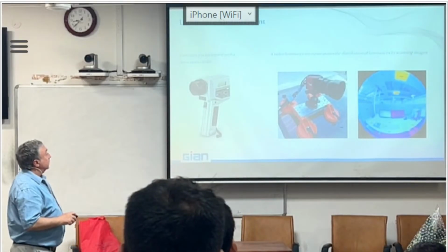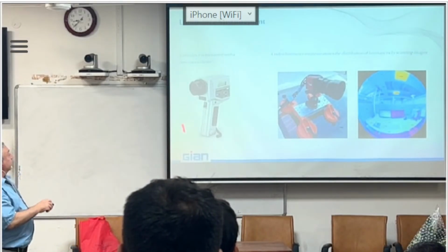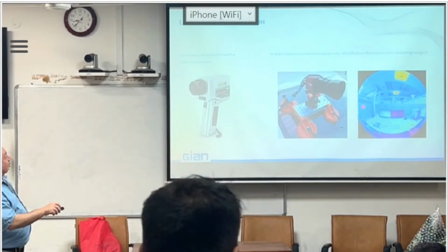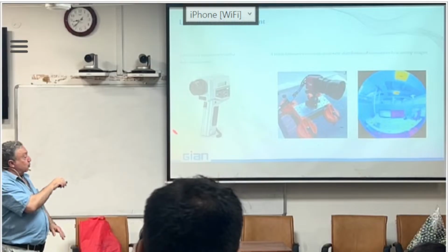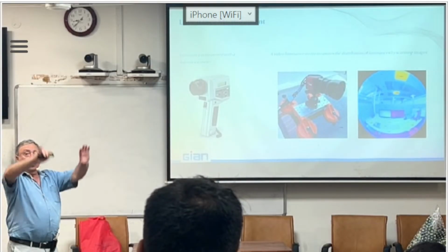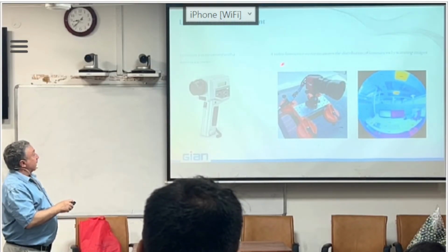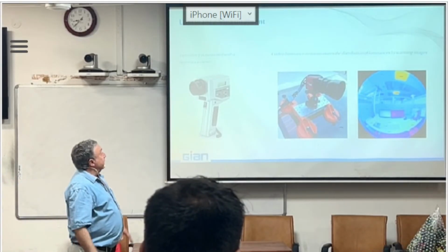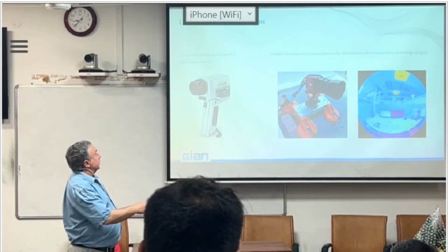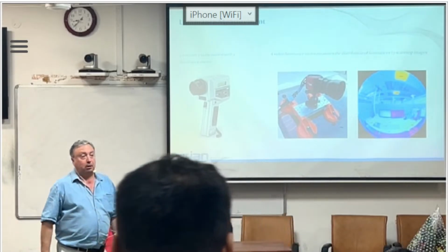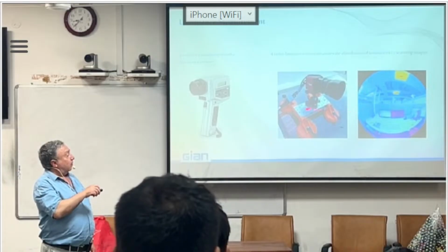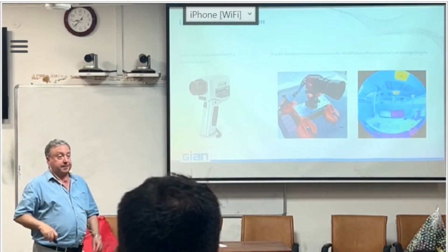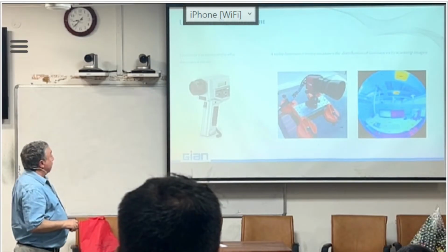How do we measure that? We measure it with luminance meters. They are this kind, if you want to measure one point. If you want to measure the full space, you can use video luminance meters, which are cameras or photo devices that can get the luminance everywhere in the space with one shot.